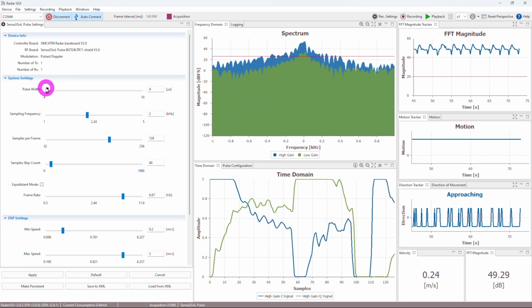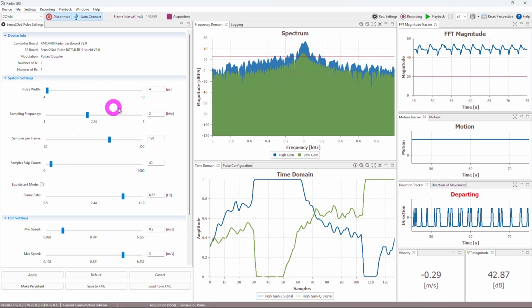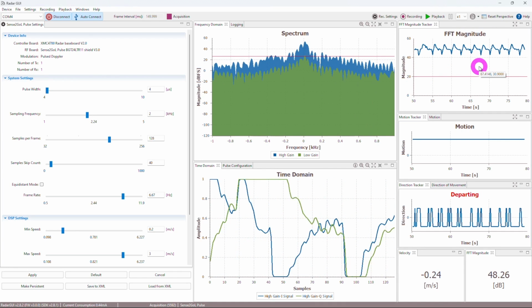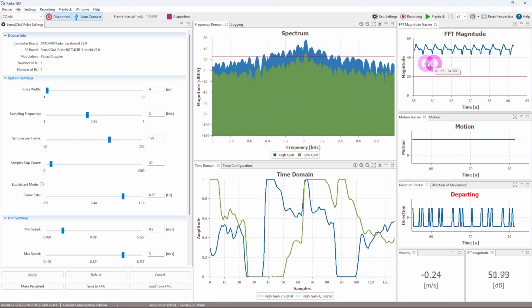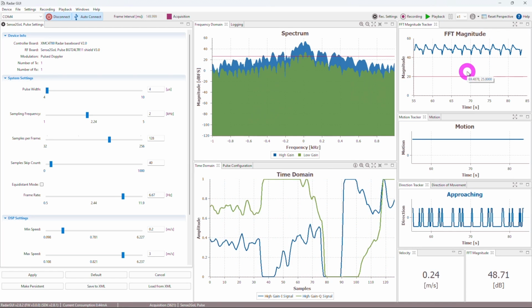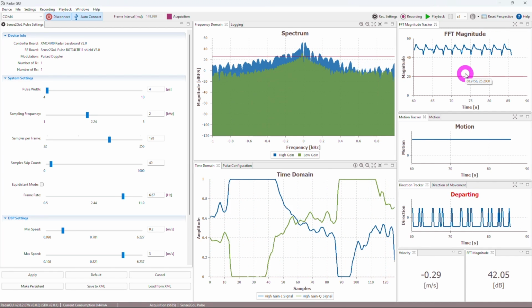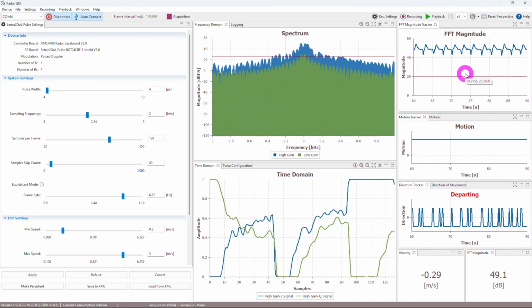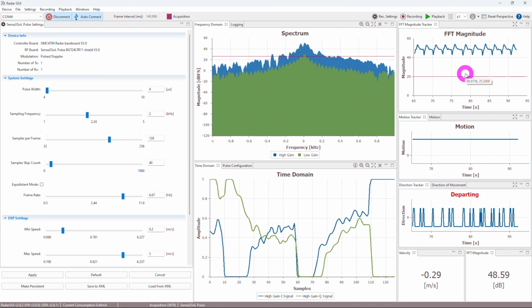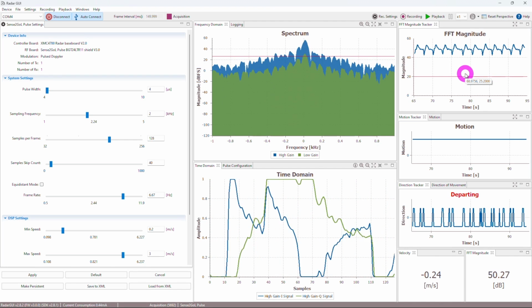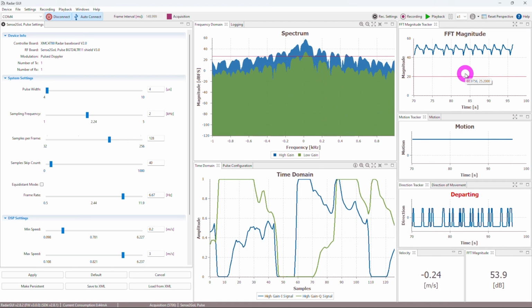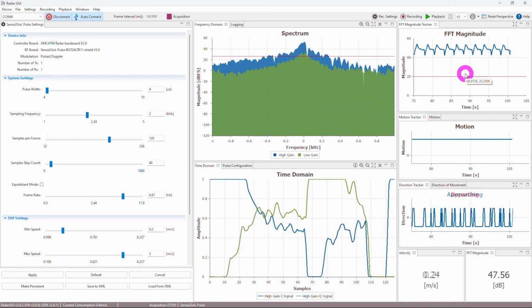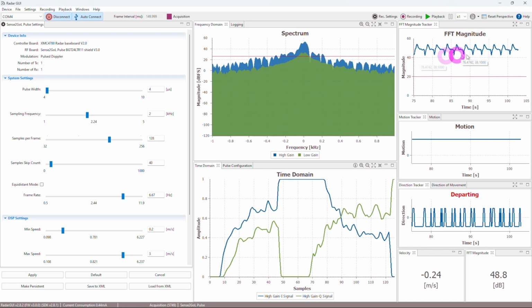Now this is not the focus here, but there is an interesting phenomenon that's worth noting in the radar. If you look at the FFT magnitude, which is the radar's computed return signal, you can see that it has this periodic behavior. Now remember that the radar is looking into the horn, and the horn is connected to the input of the spectrum analyzer. The spectrum analyzer is constantly sweeping, and it has all these front-end switches that are constantly changing. Now from the radar's point of view, the VSWR of the antenna is constantly changing too, and there may even be a little bit of leakage signal coming back out. So that looks like this periodic signal.